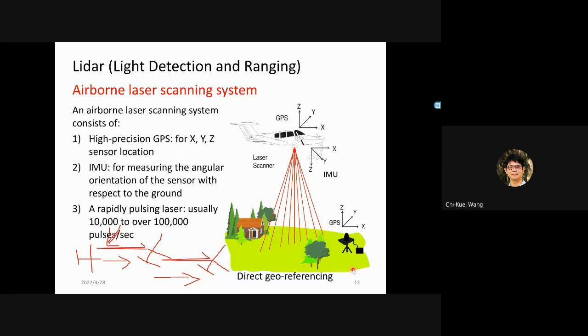And there's actually another consideration. If you are working on a larger project, where you want to measure the geometry, if you want to map a larger area of your country, you would definitely want a ground-based GPS base here, because that will help you to solve the local coordinate system problem.